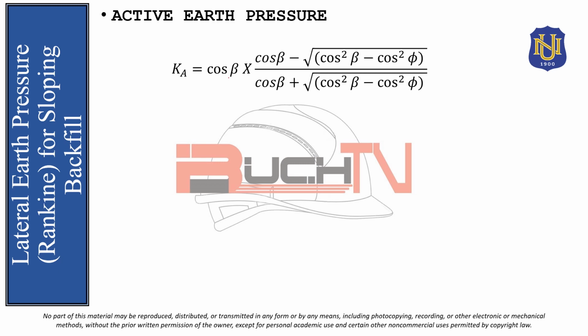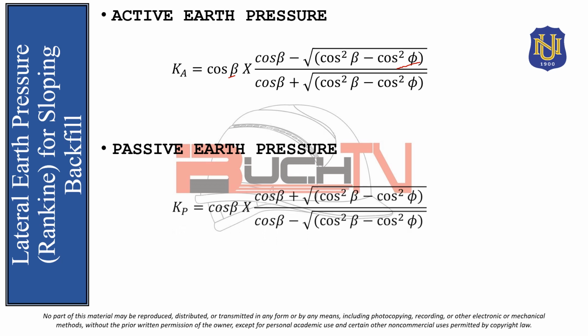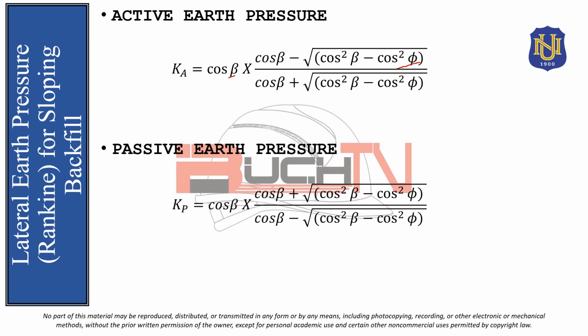So, yung beta dito is the inclination of the backfill. Then yung phi is the angle of internal friction or the angle of shearing resistance. So, kung pupunta tayo on the side of the passive earth pressure, that will be K sub P is equal to cosine of beta times cosine of beta plus square root of cosine squared of beta minus cosine squared of phi, divided by cosine of beta minus square root of cosine squared of beta minus cosine squared of phi.